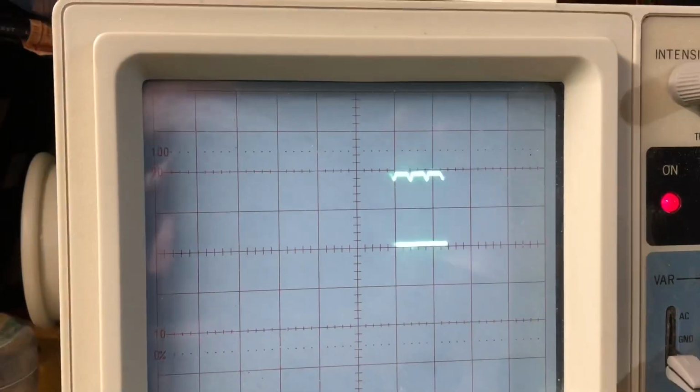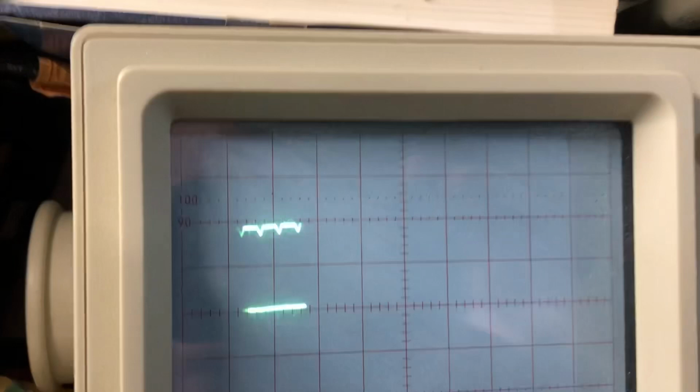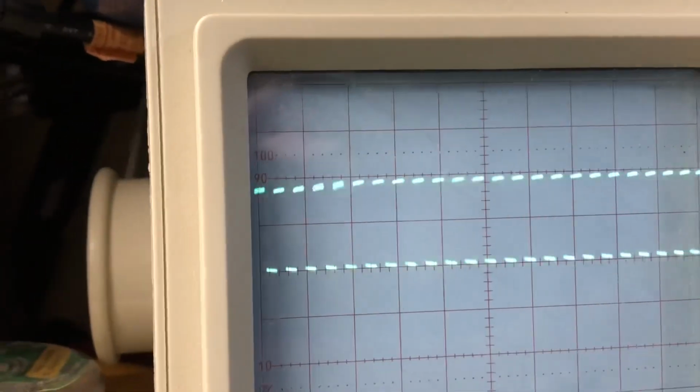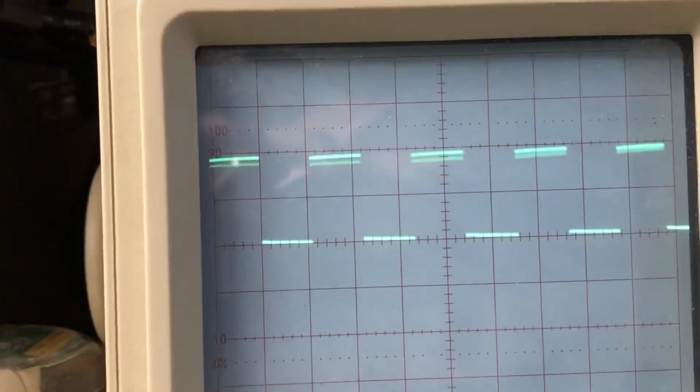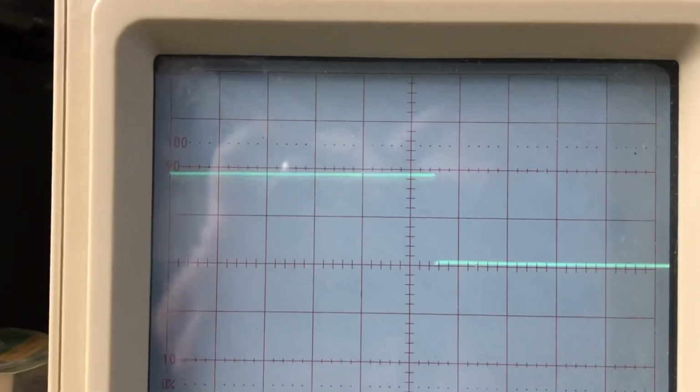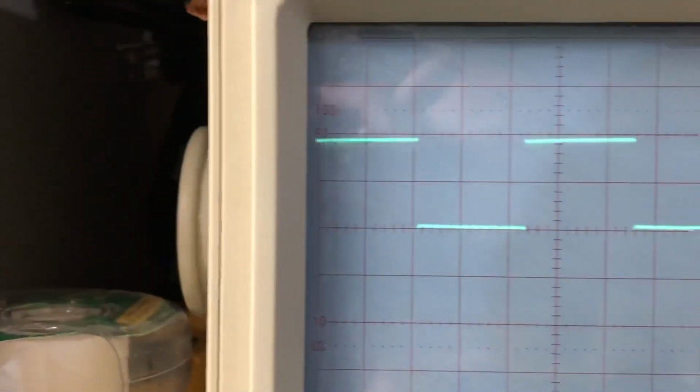All right, so see those gaps in the trace there? Those are the characters. So if I zoom in on this, I can see a good clock. I can count on the screen and measure the frequency that way, which I did, and I checked it, and it looks close, but it's hard to tell on this old thing.